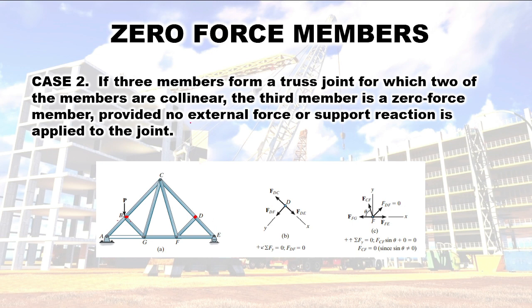Then, provided no external force or support reaction. In this one, meron tayong external load. So, our third member here is not a zero force member. How about here, our FD? Is it a zero force member? Yes, it is a zero force member because you don't have reactions here or external loads. So that is your zero force member.